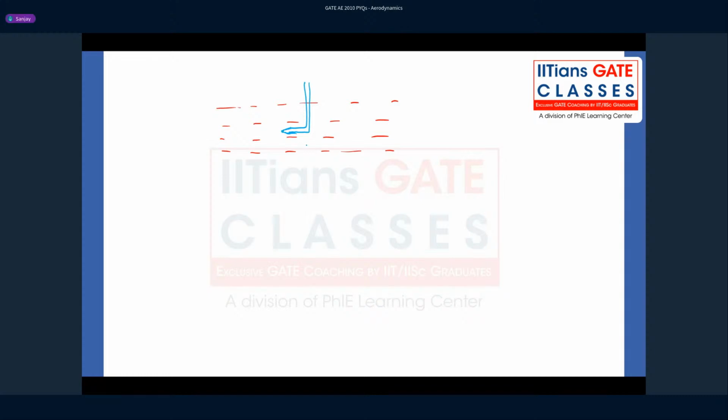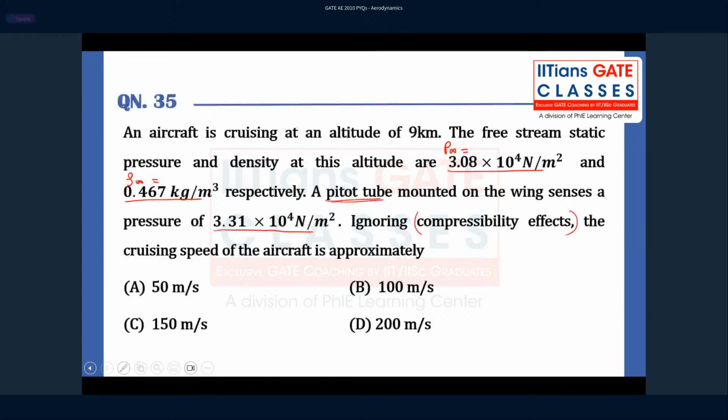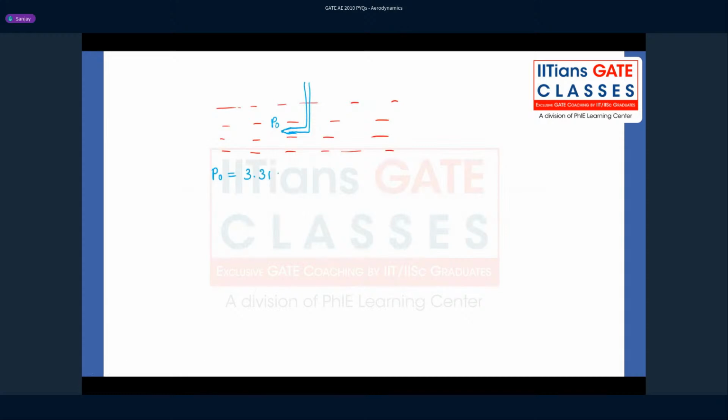Pitot tube measures the stagnation pressure, right? So what it measures is basically P naught. Okay. So the flow will come and stagnate at the nose of this Pitot probe, and what it measures is the stagnation pressure P naught. So you are given the P naught value, right? What is that? 3.31 into 10 power 4 Newton per meter square.